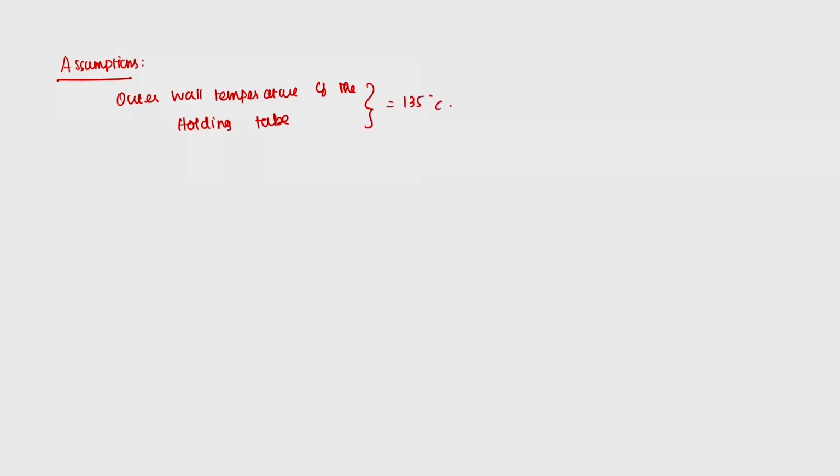And one more thing is, there is no fouling resistance, because I am not going to calculate the overall heat transfer coefficient. Fouling resistance in the sense, when the heat is conducted from the product to the tube wall of the heat exchanger, there is no fouling factor. So, because of which there is no heat resistance. That is why we said the product is at the outer wall, the temperature is nothing but 135 degree itself. And one more thing is, I need to calculate the outer diameter.